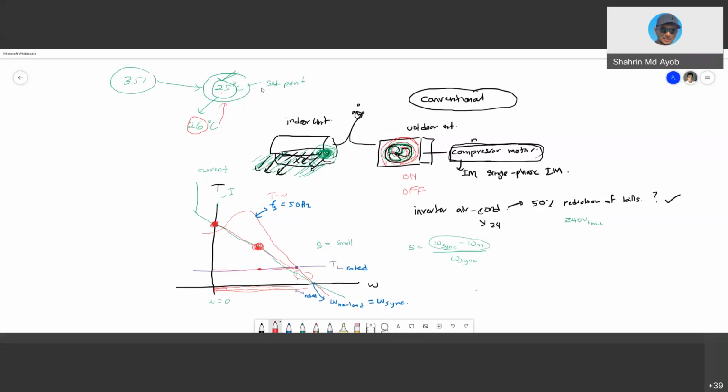So, to save energy, what we need to do is introduce this inverter. Inside that aircon, we have the AC supply, 240 volts, and then we convert from AC to DC, which is what we call the rectifier, and then from this DC we convert back to AC. This one we call the inverter. And then we have this one, your motor. A single phase motor, with this inverter.